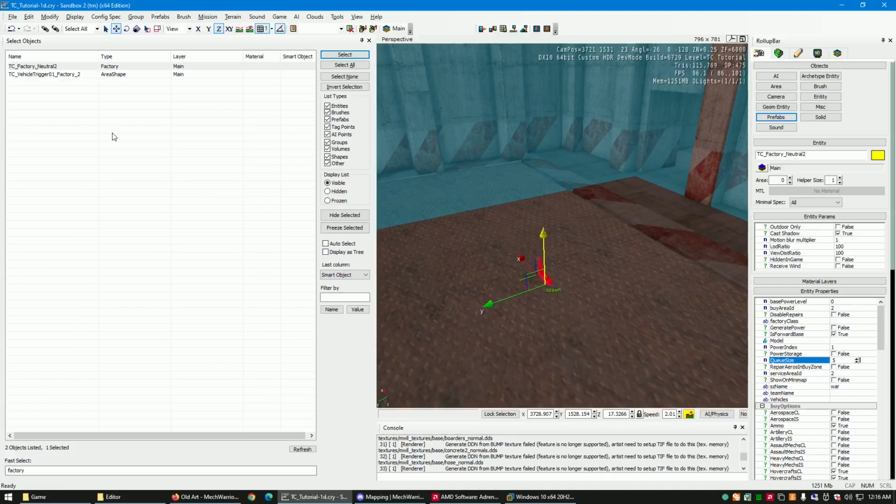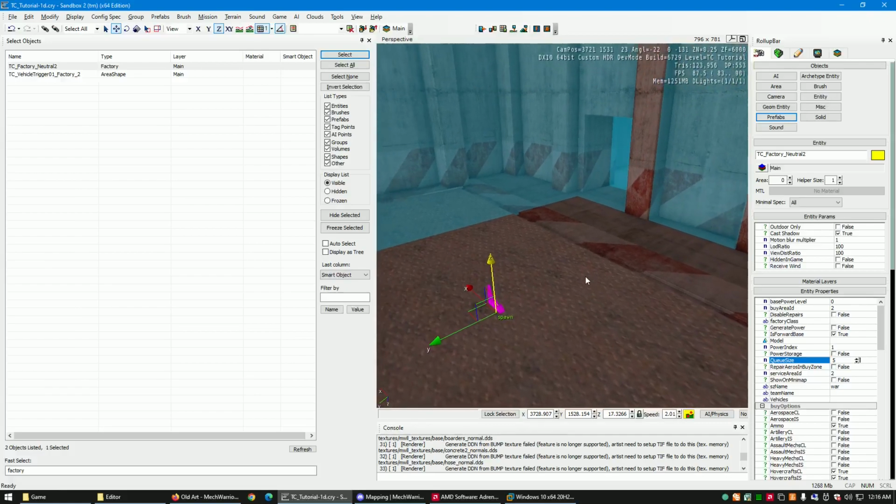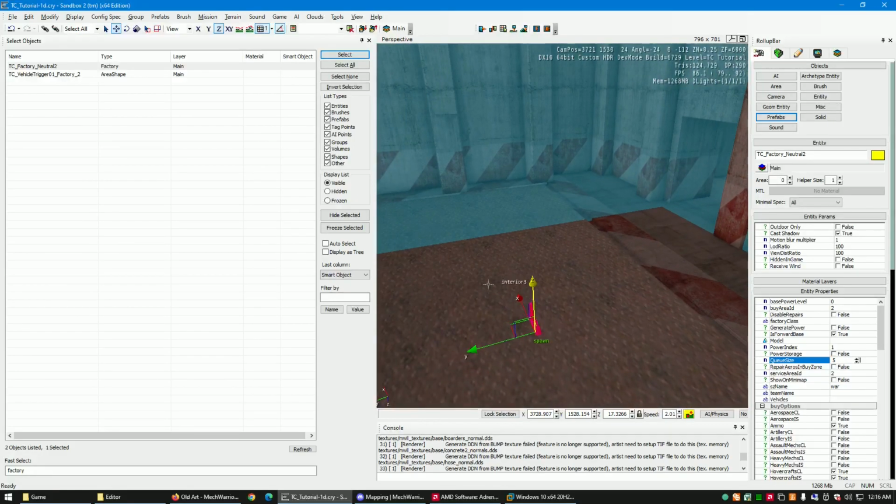You can reduce the amount of things that you can see right here. You can set multiple objects. And most importantly, you have to be very careful about this. If you set something by mistake to frozen or hidden, you will not see it here. You will not be able to click on it if it's frozen. And you'll be very frustrated figuring out, why can't I click on this object? It's because most likely it's frozen. And if you can't find it anywhere, it's because it's most likely hidden.